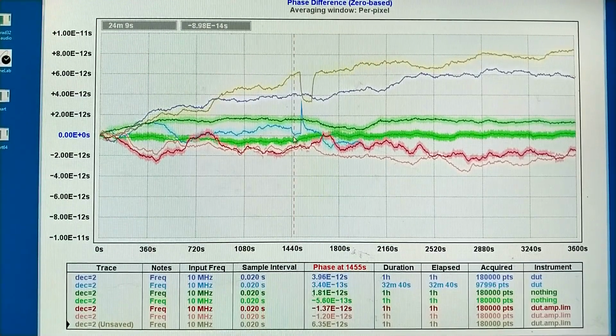I will try to optimize this setup and then try to find out exactly what is the origin of the phase noise I see through the amplifier. Because phase noise means changes of the phase through the oscillator, and the oscillation frequency is where the phase is 0. So if the frequency where the phase shift is 0 varies, I will have phase modulation, phase noise.